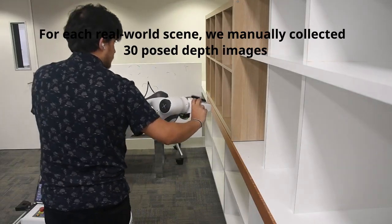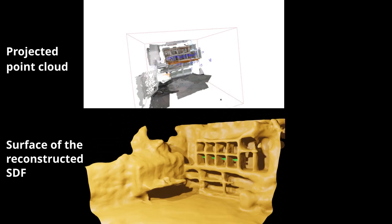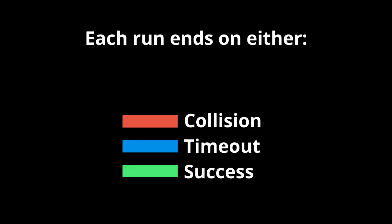We tested our approach on a real-world platform. In order to model the scenes as SDFs, we manually collect 30 posed depth images for each scene and then use iSDF to reconstruct them. Our experiments consisted of a reaching task in which the robot needed to reach different predefined target poses. Each run ends with a collision if the robot collides, a timeout when the robot gets stuck, and a success when the robot manages to reach the target pose with a margin of 2 centimeters.